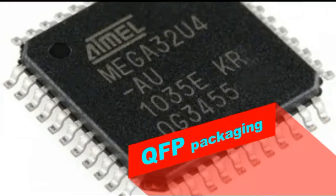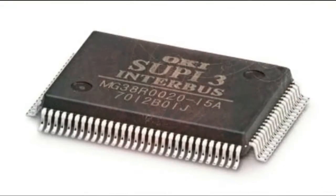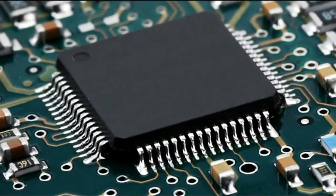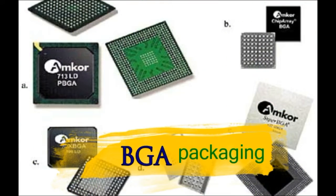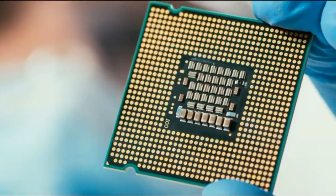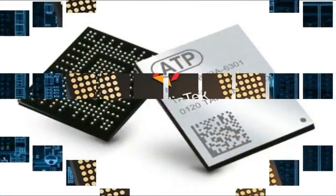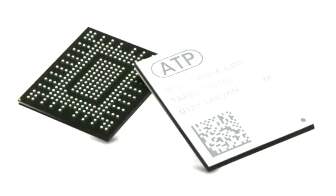QFP packaging, quad flat package. In this type of packaging, IC bases are connected to the four sides of the IC in a square or rectangular form. These packages replace DIP packages and are used for complex ICs with more pins. BGA packaging, ball grid array. In this type of packaging, IC bases are placed under the IC in the form of small balls and connected to the board in a grid. These packages are used as a suitable alternative for ICs with high capabilities and more heat.